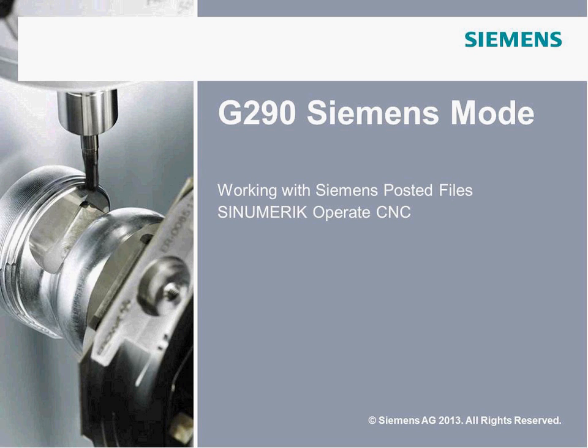What we do is we start looking at our G290 mode, which is what we call our Siemens mode. Really, a lot of people don't realize it, but whenever you're in the Siemens protocol, and when I say Siemens protocol, it's just really what the commands are, how they affect the machine. You're actually running in G290 mode, so you'll hear me refer to it as G290 mode. So you don't have to actually tell it to be in G290 mode. The system does it all automatically, but you could in your part program if you wanted to.